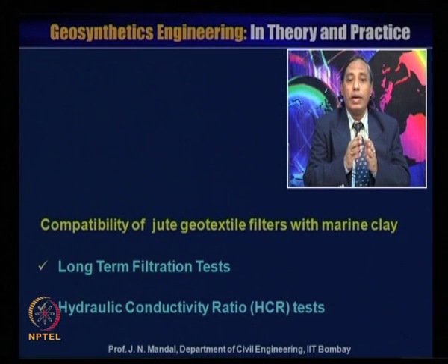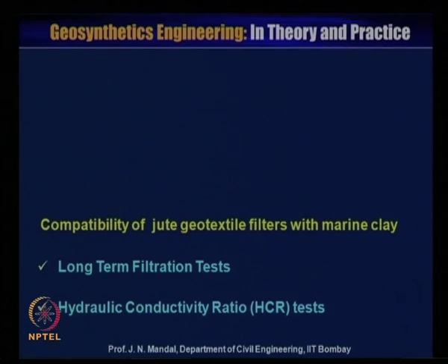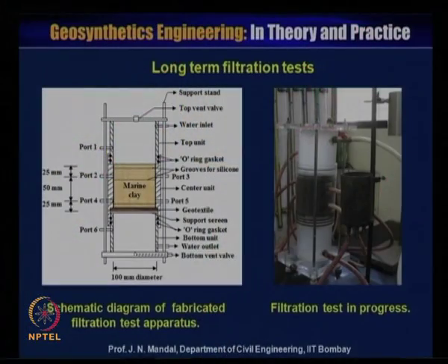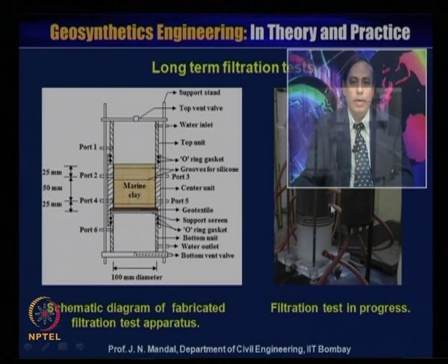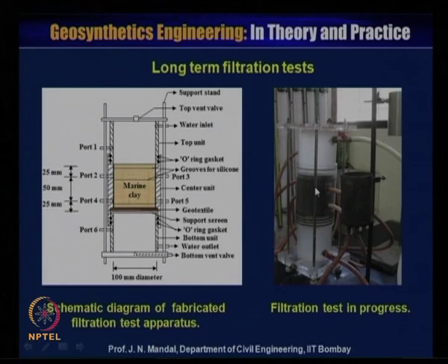It requires the hydraulic conductivity ratio test, that is called the HCR test. So, for the long term filtration test, this is the schematic diagram, and this filtration test apparatus was fabricated at IIT Bombay by Dr. Asha, and the filtration test is in progress.